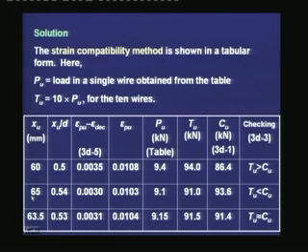What we find is we first started with an assumed depth of 60 millimeters, which is half of the effective depth. Xu by d is half, which is 0.5, and from there we find that the tension is 94 kilonewtons and the compression is 86.4 kilonewtons. For this step, the tension is greater than the compression. Hence, we need to have a larger Xu to give more compression in the concrete.